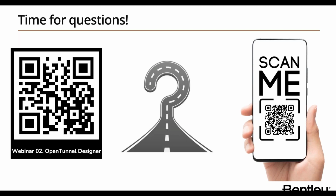Excellent. Thank you, Vlad. Third one, how do you parameterize the model templates to follow road widenings? Those ones will have to be done by splitting the tunnel in units. So if I know that I will need to, let's say, enlarge, to loft a section from a smaller geometry to a bigger geometry, I'll have to split the tunnel. One tunnel will be with a constant section, and the second tunnel will be with a linear transition unit. In there, you will have two different cross sections.